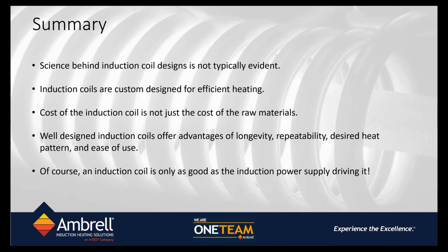So there's always a give and take between how many turns you are able to put in versus the efficiency of the system, to be able to get the best induction setup. Ideally, if you could put 1,000,000 turns, you'd have the best type of heating, because you'd have such a good transformer effect between the coil and the part. But it's not practical. So that's where you need to know what induction machine you have, how easy it is to change stuff, and how well its automatic tuning works to be able to then match to the induction heating coil that you designed.